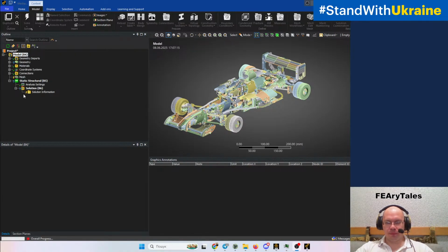So, yep, it's already open. Almost. Now it's detecting the mesh, detecting contacts. That's one of the reasons why on a previous video I said that it's more sufficient to open different sub-assemblies and then create the mesh assembly inside of Ansys Workbench.